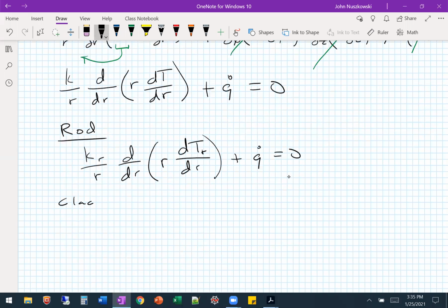So for the cladding, do we have to change this heat equation for the cladding? We just need to add in K sub C and R outer, right? Well, yeah, R outer goes with the boundary conditions. Is there anything we cancel in the cladding material? Q dot, we can get rid of that.